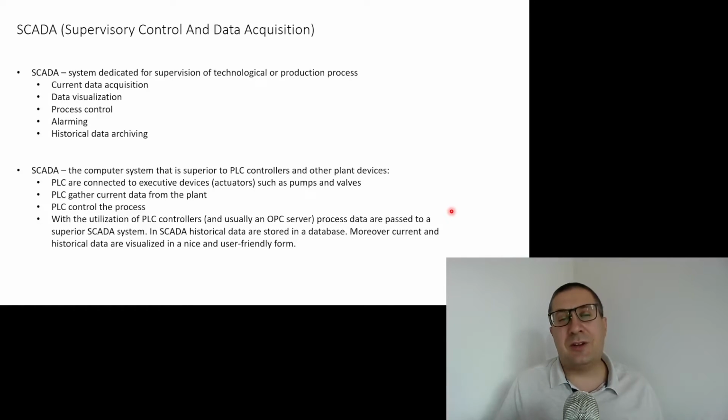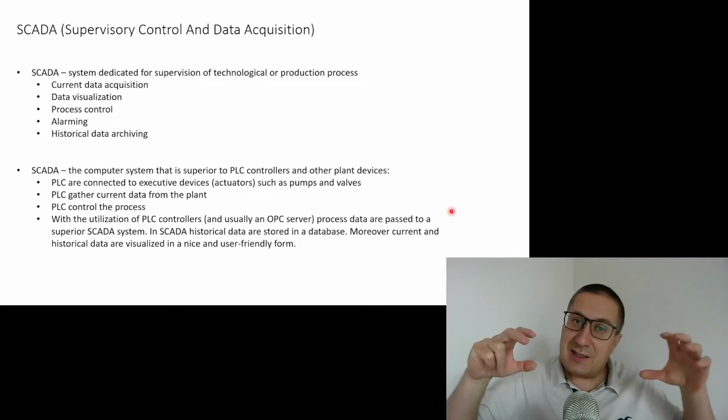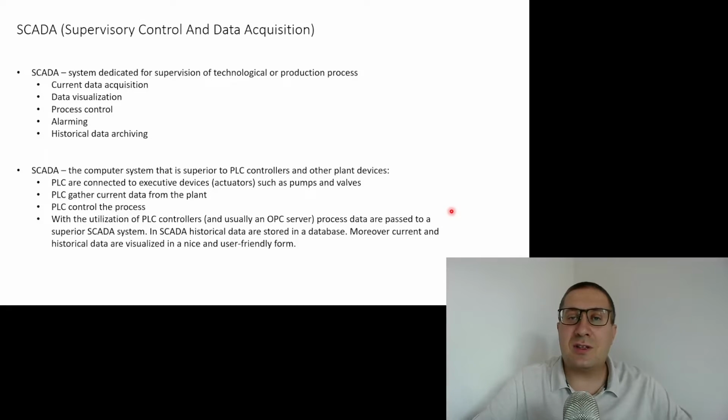And the SCADA system is superior to PLC controllers. So PLC controllers are connected to devices, right? To actuators and sensors. They are sending decisions to actuators. They are reading sensor values and processing them, right? They are performing the control algorithms. But from the SCADA system, we can send our decisions to controllers. We can see the sensor values. We can store the historical data.